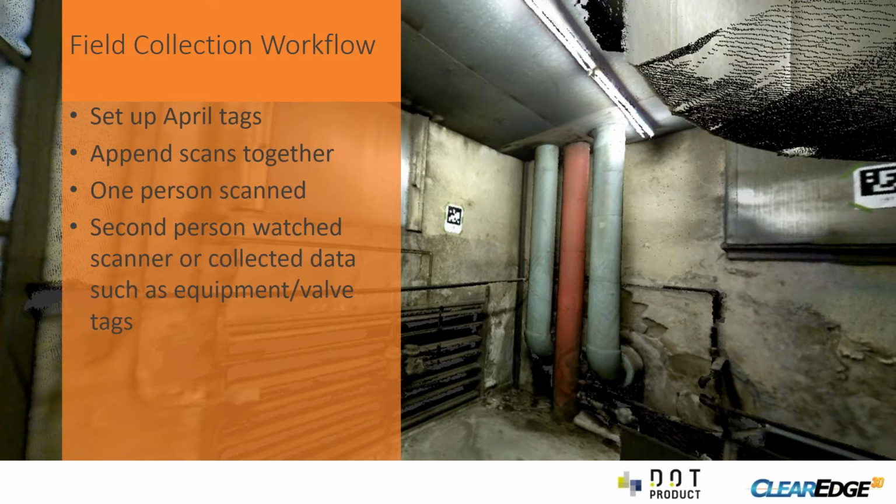One person ran the scanner, while the second person watched the person who was scanning, to make sure they weren't going to trip over any drain valves or bump into any valve stems or anything like that. And if the person scanning was in a nice environment where they didn't really need to be watched, the second person went around, collected equipment data, so valve tags, equipment tags, took any readings from pressure gauges or temperature gauges, things like that.